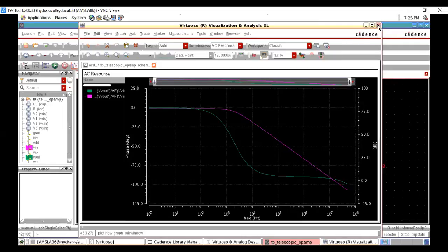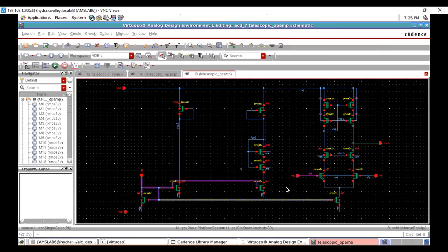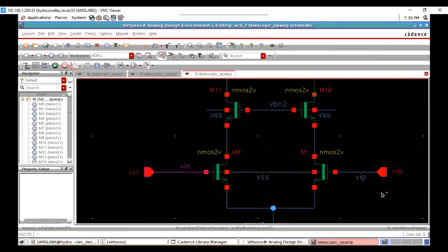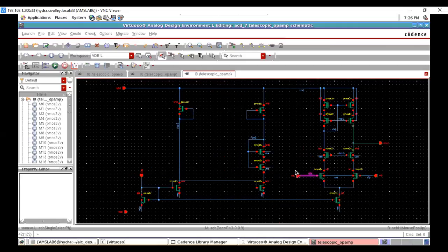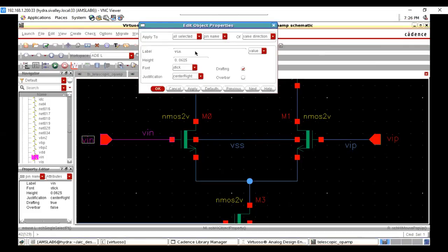See what happened is, this is a single stage op amp, so the input terminals are swapped. I just kept the same as that of the 2 stage, but actually this is the positive terminal and this is the negative terminal, right? See, the names are reversed. This is negative, this is positive, it is telling. That's why, by looking at the outside, I drew it with respect to the input, so it came reversed, starting at 180. Okay, did you get it?